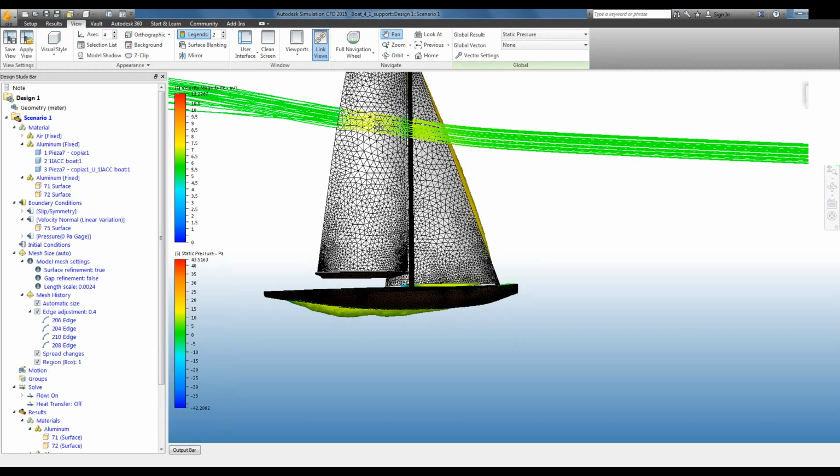Spherical can work, except you've got to figure out how you're going to transition from your inlet condition, which is possibly going to be a specified velocity, to that pressure condition to let the flow actually proceed out of the domain. One of the issues is if you have a sphere, and you have two hemispherical, I guess they're actually quarter spherical surfaces, you're going to have a line demarcating between them, and on that line you're going to have both a velocity and a pressure condition applied, and that can cause issues because it's not physically real. If you can think to separate that, that works.